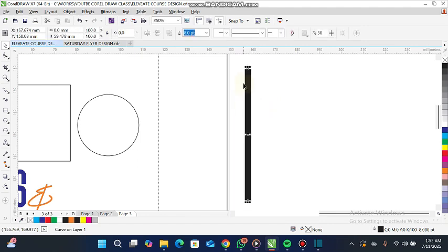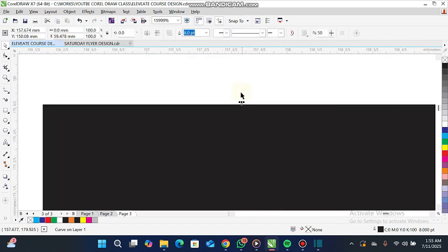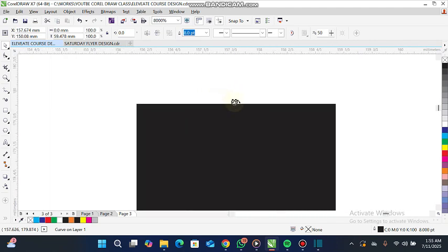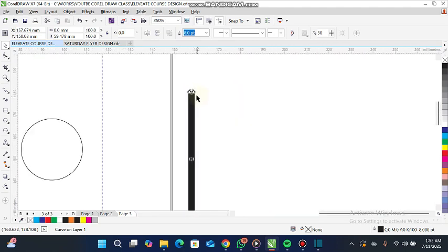Okay, now I have to duplicate this thing. I need it to be in a fan way. So I will click once. When I click once, there's a box around it. But when I click it again, you notice that there are arrows facing different directions. So I will click, my mouse will turn to a semicircle arrow, and wherever point I want it to go, I will drag my mouse that way.